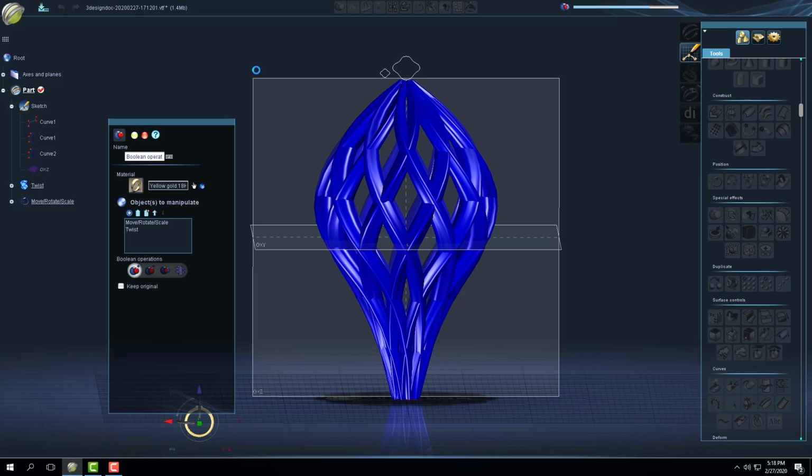And you can see this Boolean is taking a lot longer than our previous one because there's a lot of intersecting points. Yeah, connections. Exactly. And even if it were able to combine two surfaces that Boolean them together, once it gets to 3D printing, the 3D printer won't know how to handle that. So it'll usually just create a void. So there's a lot of intersections going on down here.